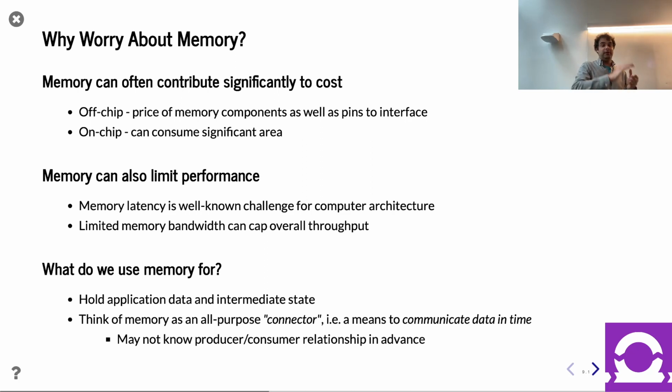And so actually, to really drive this point home, if you look at the newest Intel Sapphire Rapids, which came out and was benchmarked only recently, for some workloads there's like a 4x difference, with the exact same CPU socket, depending on whether data is coming from DDR or from HBM. And that tells you the importance of bandwidth. It's a bandwidth limited workload. If you give more bandwidth, it can go faster. And if you don't have enough bandwidth, you're limited. So bandwidth is really important. Latency of memory is really important.